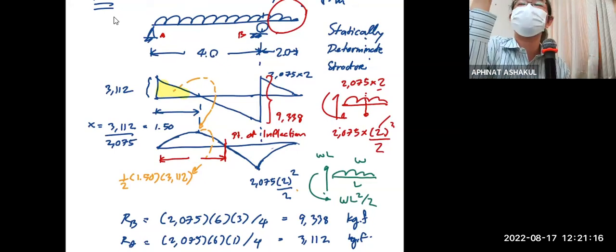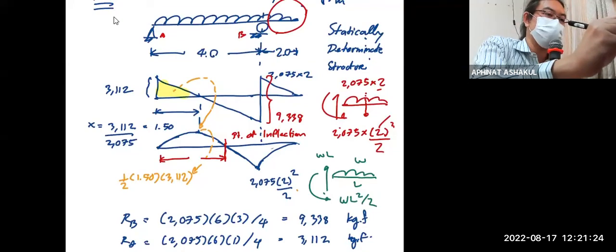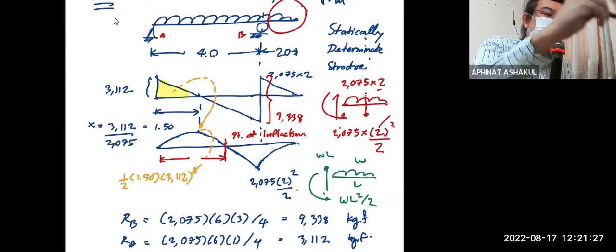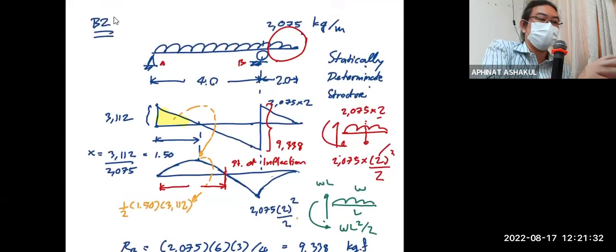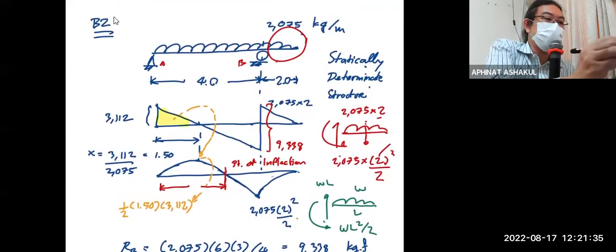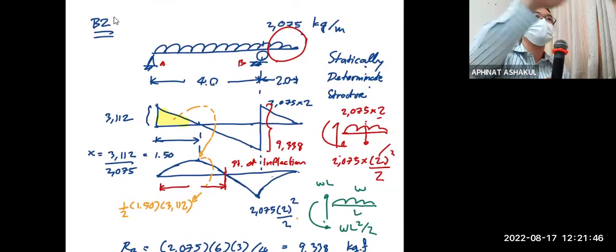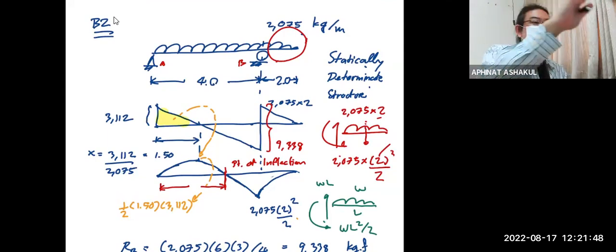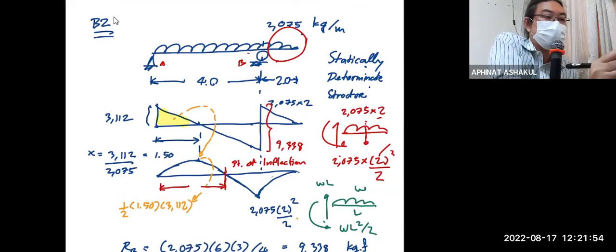You have calculated the deflection of the beam before, right? But are you aware that when you look at the beam, you can actually tell or guess how your beam is going to deform or deflect? And when you look at this kind of load, this is the overhanging portion, correct? So when your beam is going to deflect here, how should it deflect? It has to come down like this. Hope you can see, here, like that. Or I can draw the line. It should deform like this.